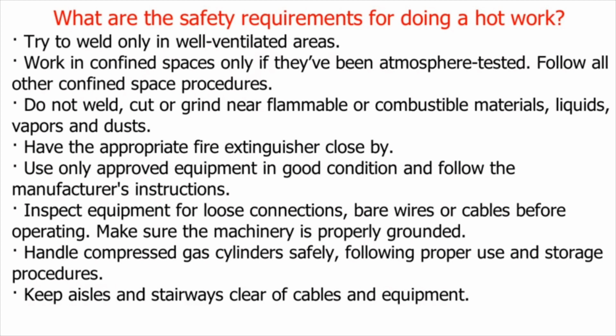Have the appropriate fire extinguisher close by. Use only approved equipment in good condition and follow the manufacturer's instructions. Inspect equipment for loose connections, bare wires or cables before operating. Make sure the machinery is properly grounded. Handle compressed gas cylinders safely, following proper use and storage procedures.